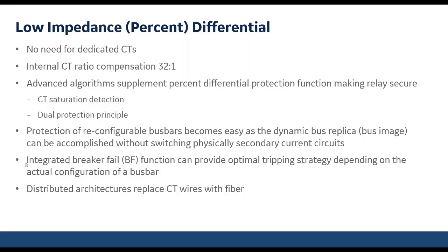We can use it for multiple users. We could use it for breaker failure. We could use it for auto reclosing. We can reuse the same CT for different functions. You don't have to have a dedicated CT for every function like in the high impedance scheme.